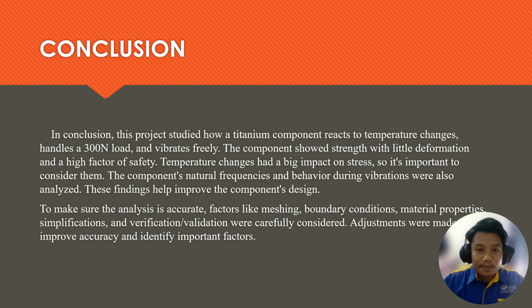In conclusion, this project studied how a titanium component reacts to temperature changes, handles 300 Newton loads, and vibrates freely. The component showed strength with little deformation and a high factor of safety. Temperature changes had a big impact on stress, so it's important to consider them. The component's natural frequencies and behavior during vibrations were also analyzed. These findings help improve the component's design.